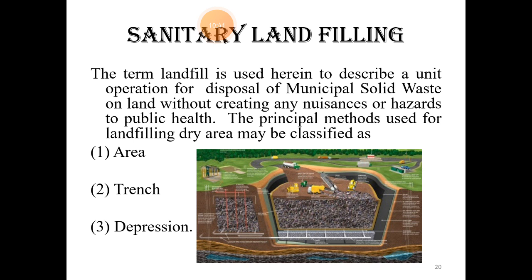The next disposal method is sanitary landfilling. It is a scientific method of disposal of solid waste on land without creating any nuisance or hazards to public health. The site of disposal here includes any dry area or even a trench or any depressed land.